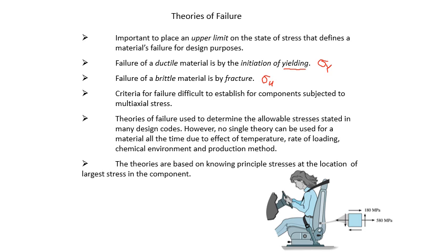Criteria for failure is difficult to establish for components subjected to multi-axial stresses. So normally manual calculation is done for simple 2D stress conditions, but for more complex components, we will need to use the finite element analysis approach to determine the principal stresses.